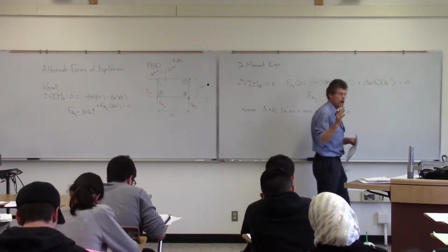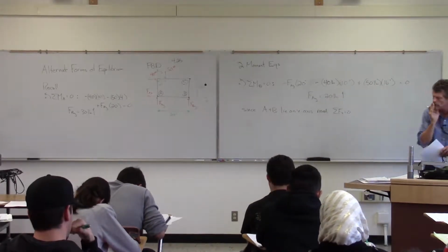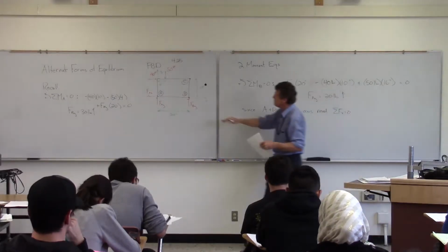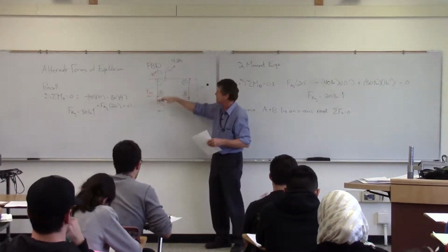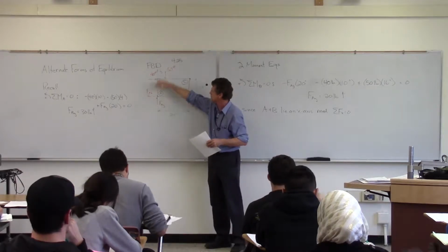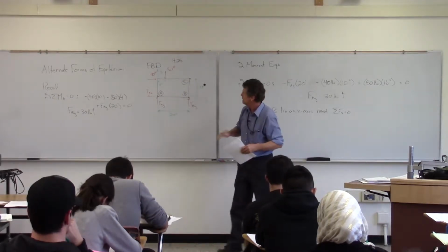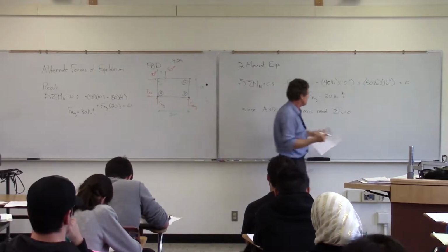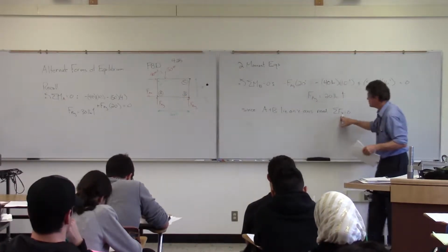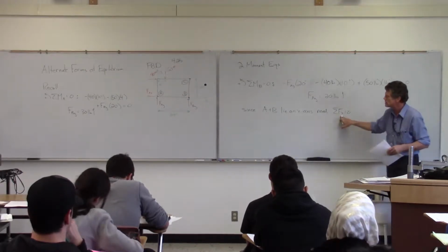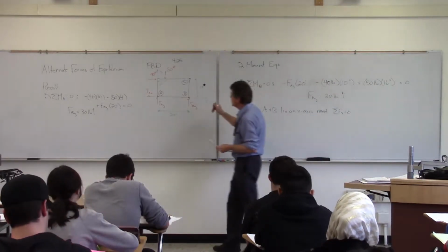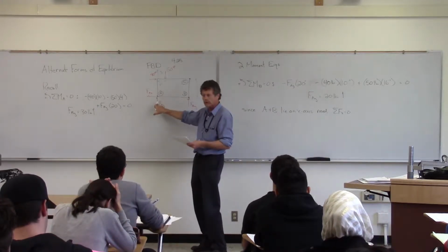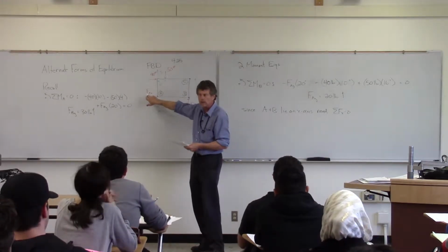Okay, so for my third equation, I've got to take a look here. And since both of them lie on the x-axis, when we think about that, I'm not changing any y dimensions there. Everything I do is going to be the same. The 40 is going to be 10 away. That's the only one that I have to worry about there. Since they lie on that x-axis, my third equation has to be the sum of forces in the x direction, which, when you look at it, makes sense. We've just solved for BY, we solved for AY. The only piece it's missing is the AX.